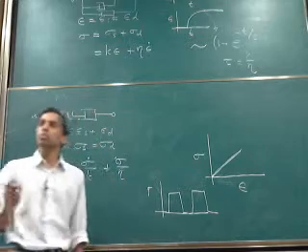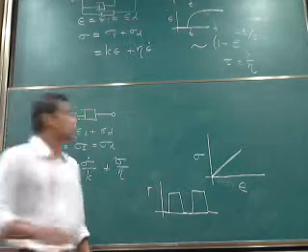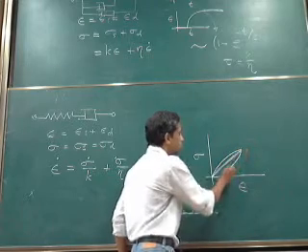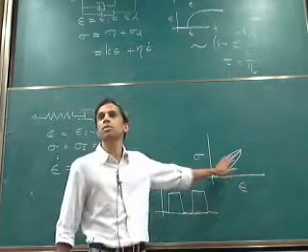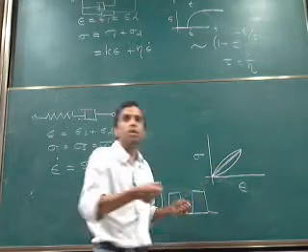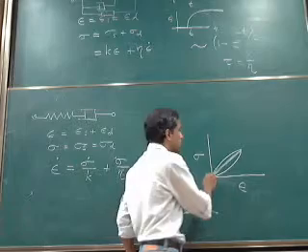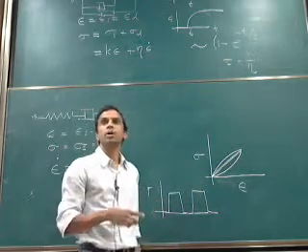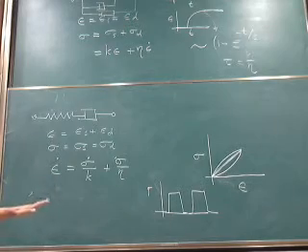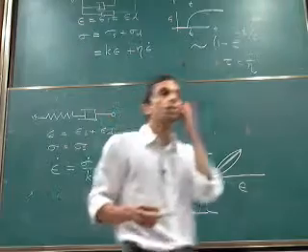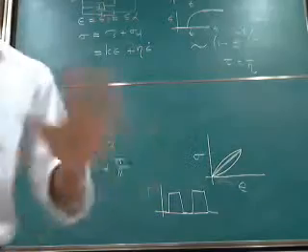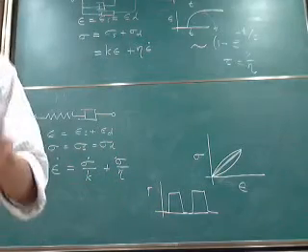Okay, but if I have viscoelastic material or viscoelastic solid, then there is dissipation. So then in that case, this will not be a straight line. This will always be a loop. Okay, this will have the curve. When I stretch the material and when I bring it back, the curve will not retrace itself. Okay, because of the relaxation which is happening in the material and dissipation which is happening. Okay. Isn't this also seen in Hookean material? This is hysteresis, right? If you see hysteresis, it's not an ideal spring. Okay, or it's not an ideal elastic material.